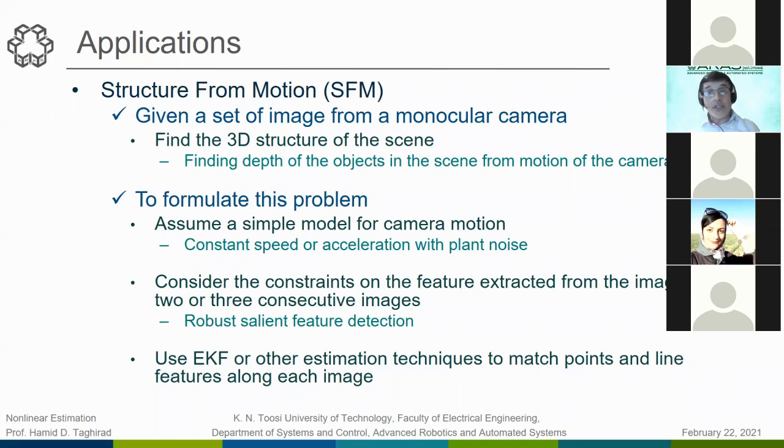We can have the SDRE observer here. We didn't talk about it. We also have robust observers, especially sliding mode observers and high-order twisting, highly nonlinear observers. The same thing that you see in controller design, almost the same history, can be projected into the observer design.